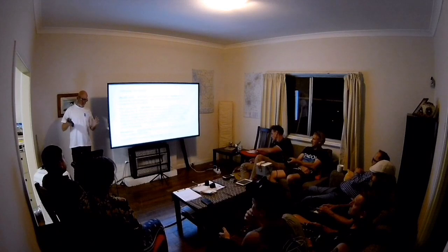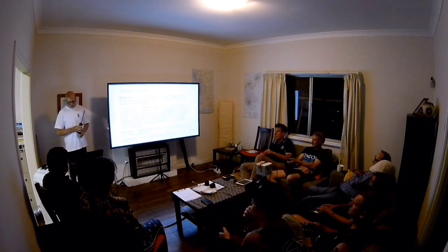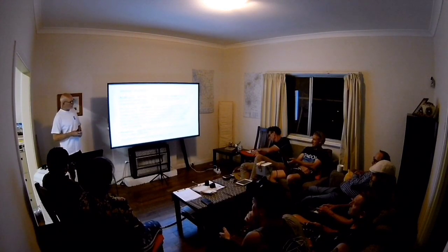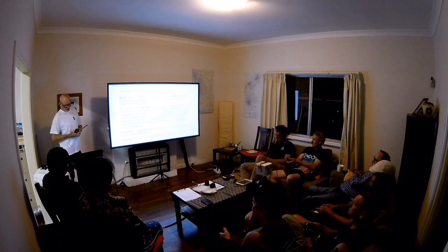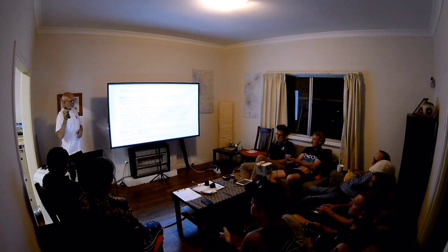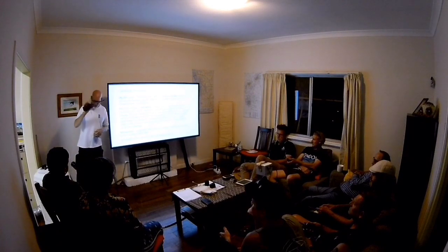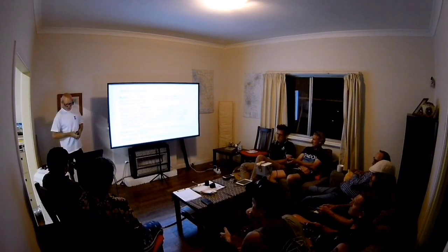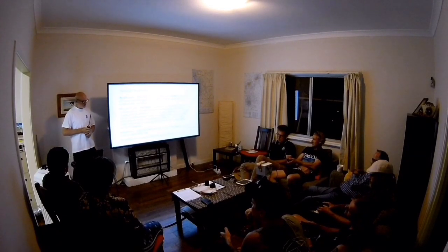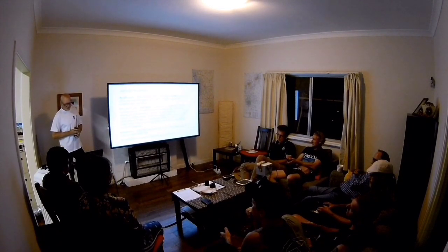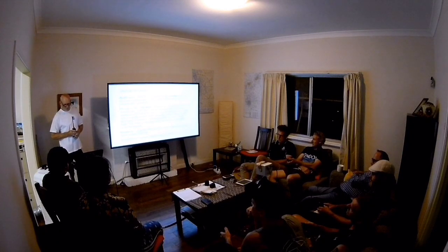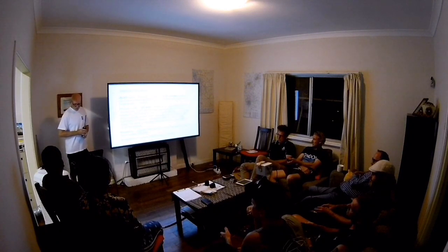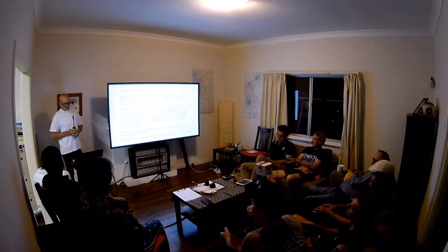PTT, push-to-talk or talk switch. The radio cannot receive and transmit at the same time. So this switch must be held down whilst transmitting, okay? And then released as soon as you've finished your message, so that the set returns to receive mode.